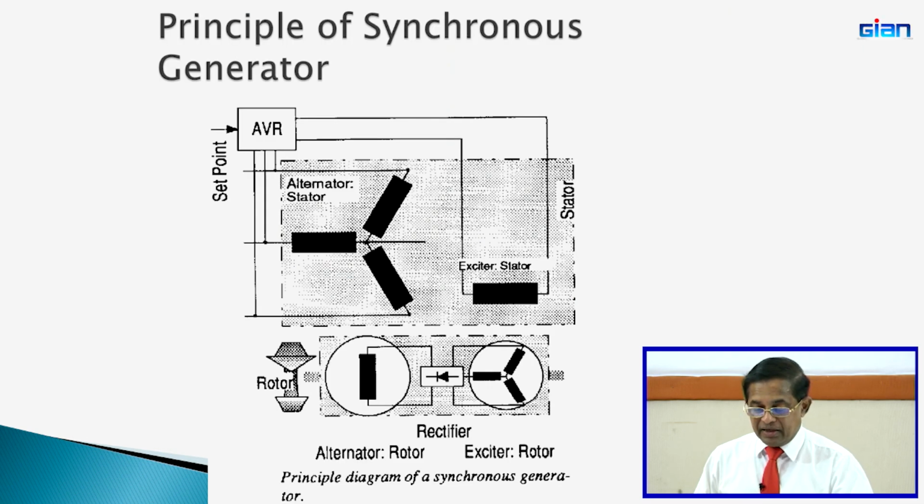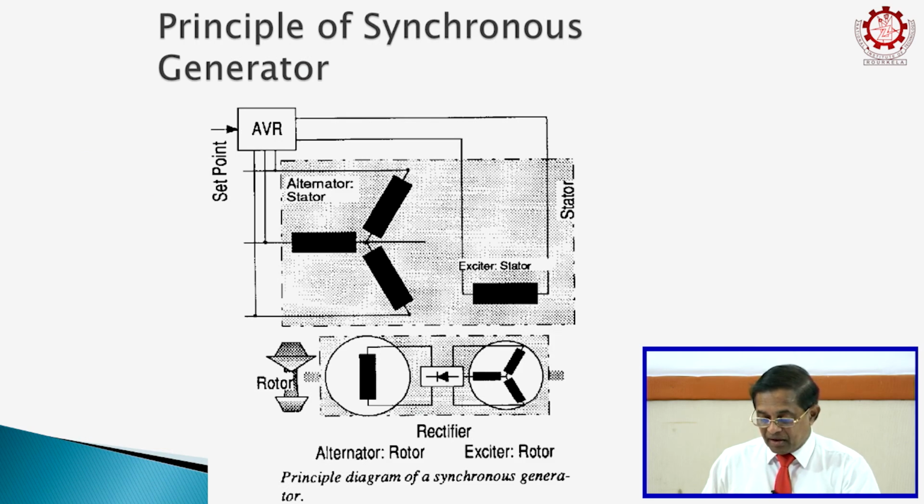So, I think we all have studied the synchronous generator. In this course we do not want to teach the operating principles, etc., in detail. What we know is there is a rotating field winding, which is usually nowadays supplied by electricity generated from a 3-phase winding mounted on the shaft, and then rectified using rotating rectifiers, and then a rotating field is created. So, usually brushless type. So that we generate DC for the poles to be magnetized. It may be a 2-pole machine, maybe a 4-pole machine, maybe an 8-pole machine or whatever, and then all will be magnetized using this DC created by rectifiers, which are also rotating and mounted at the end of the generator shaft, right.